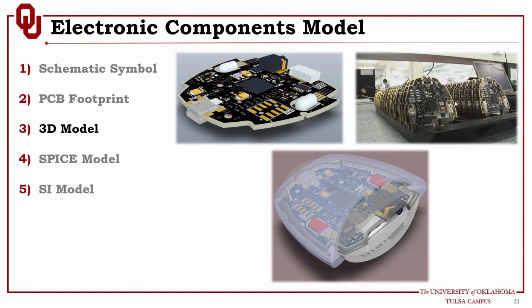And Altium Designer allows you to do that. And in this case, as we said, we need to have a 3D model for every single component on the board. This 3D model represents the actual physical size of the component, as we can see here. This is a board, courtesy of Altium. Here we can see the USB connector, the earphone connector, and the LEDs, etc. Now, within Altium Designer, we can import a 3D model for the enclosure, and we can do clearance tests to make sure that nothing from the board will interfere with the enclosure at any single point before we build the board. If anything needs to be moved or adjusted, we can do that before the build. Once we have this collaboration between mechanical design and electrical design, we can release the board and fabricate it. This is how important the 3D model is during this design.